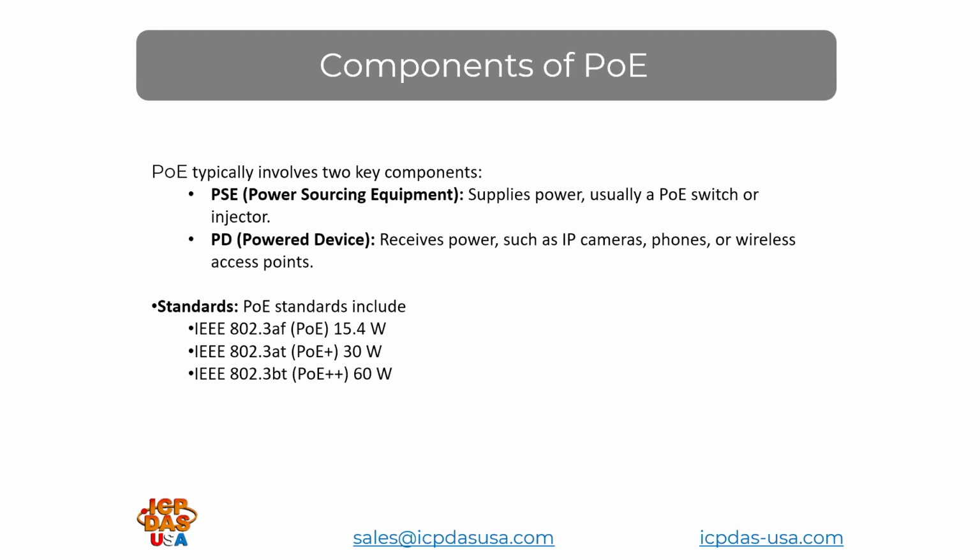And finally, there's PoE Plus Plus, which is up to 60 watts. There are a few others, but these are the main ones which industrial customers follow. Non-standard PoE is also out there, so be careful. If you use the wrong type of switches, they'll put out the wrong voltage and probably not sufficiently power your special equipment, so be careful on that.